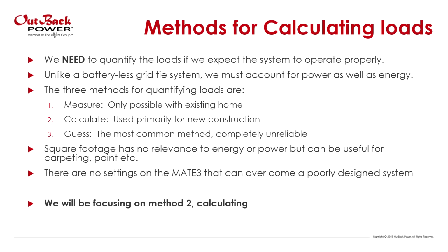Square footage, there's no correlation between square footage and solar. It's useful for other things like carpeting or paint, but when it comes to system sizing, especially off-grid system sizing, we need to deal with loads. So this step one is critical.